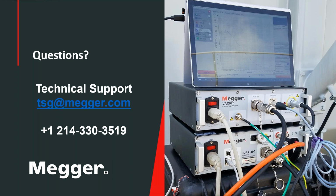Just to give you a quick example, we were looking into the traffic light assessment. For mineral oil, 0.3 or 0.4 picosiemens per meter is a very good condition. That is kind of brand new oil. But even at somewhere around 10 to 15 picosiemens per meter, the conductivity of FR3 is very good. So the differences are not in the test, but in the interpretation of the result.